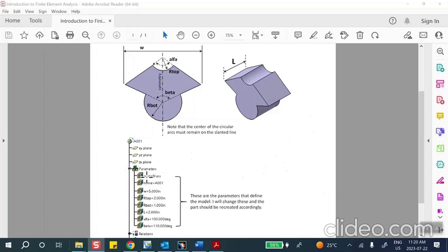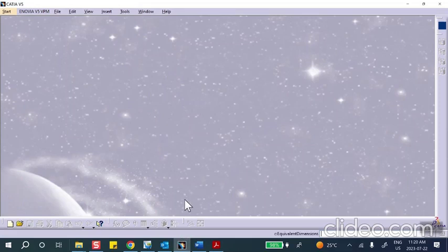I'm not creating a parameter myself. The parameter is automatically created as soon as you put material on it. But I'm going to rename that so that it doesn't say uppercase Material, it says MAT as I want it. Okay, so let's go ahead and do that. And then after that, you can create these other parameters, and finally you can do the nominal part. So let's go there.